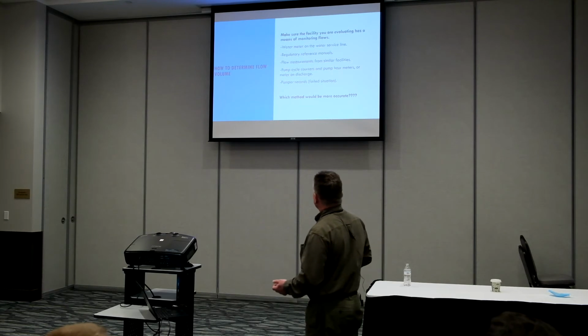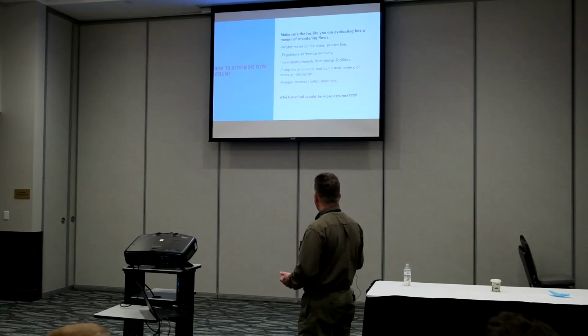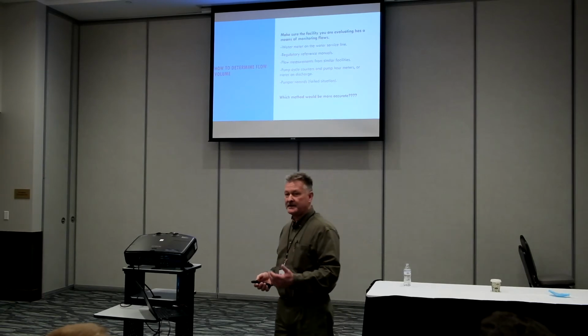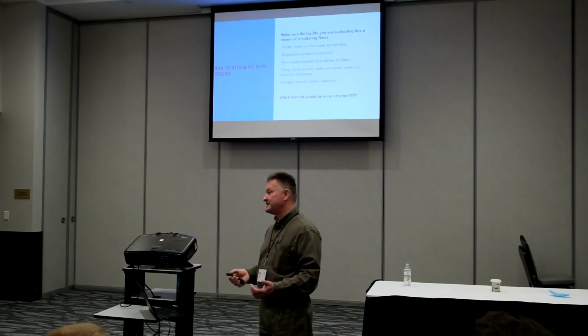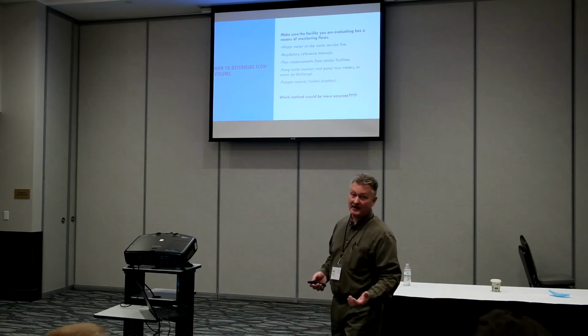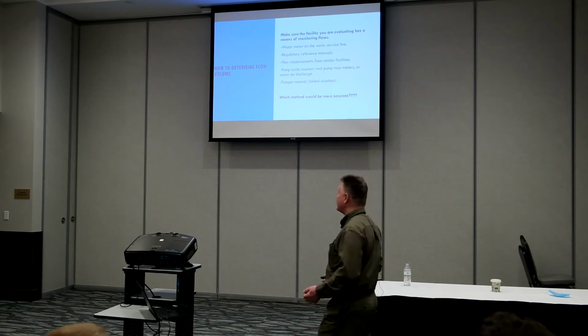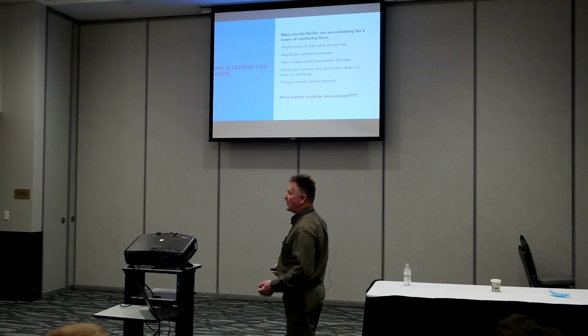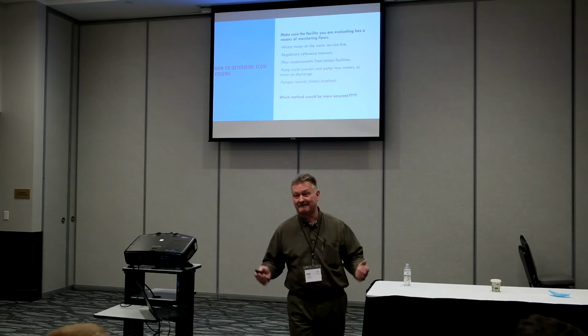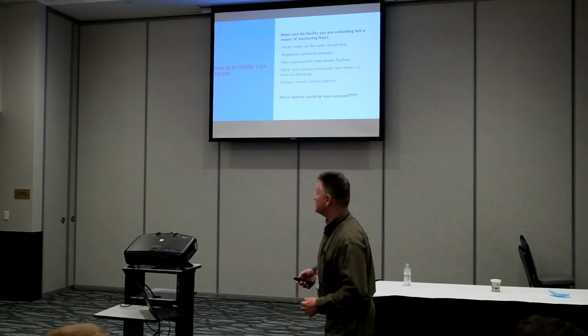Our hope is that there is a means of, and oftentimes for a lot of our rural facilities on a water well, there's no means of collecting that water. In my opinion, every water source, water well or municipal, should have a meter on there. So we don't get into a jam if we're doing a repair situation. It's like, oh, now we got to try to guess what the flows are.